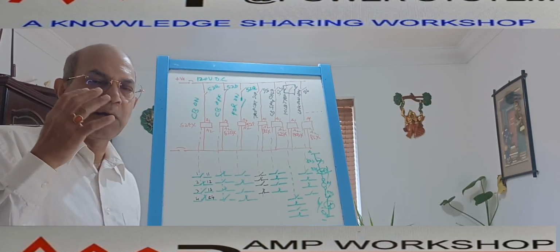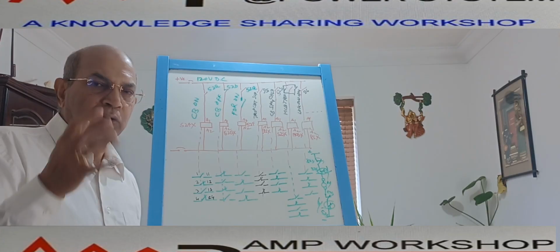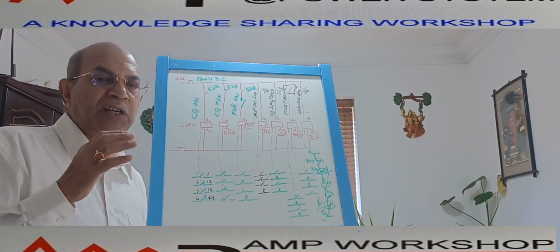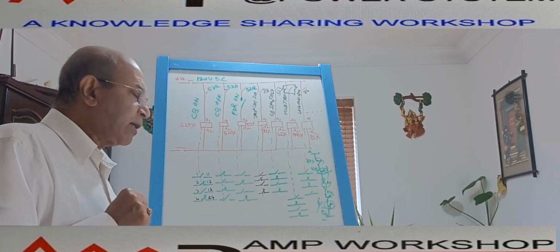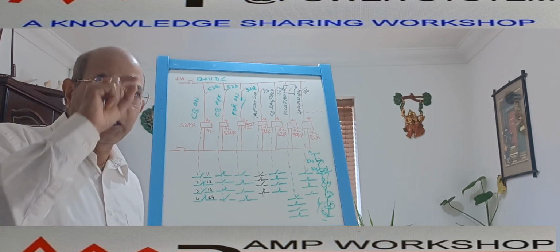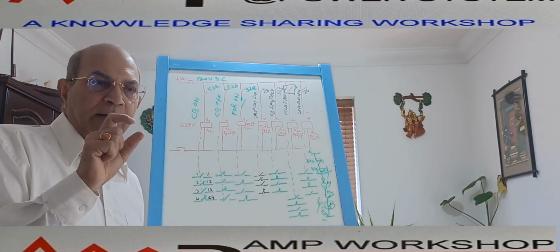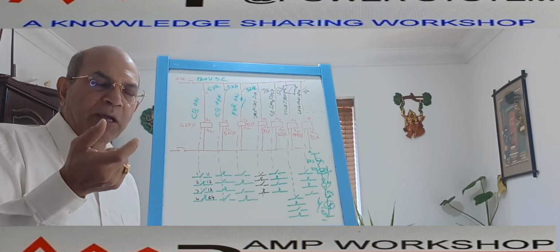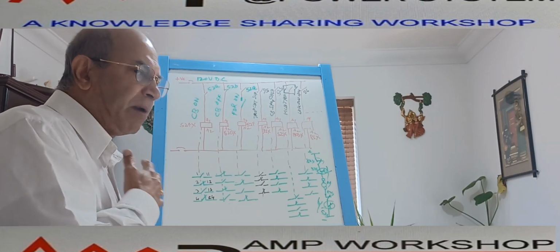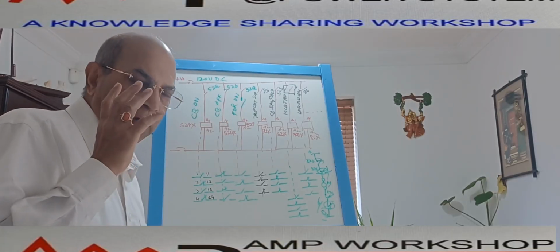At that condition, maybe we have selected an auxiliary relay which has 3 NO 3 NC contacts. When the relay is not energized, it is in the de-energized condition normally. These contacts are mounted on the spindle. When the coil gets energized, it immediately pulls the spindle or plunger, and the contacts change over, meaning NC contacts become NO and NO contacts become NC. That way the auxiliary relay operates. So we can use as many auxiliary relays as we require. I have shown this as a typical circuit breaker.